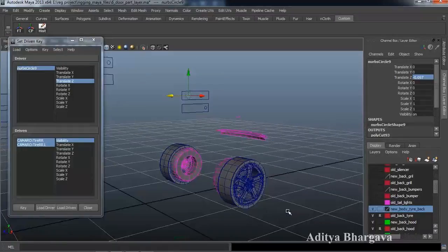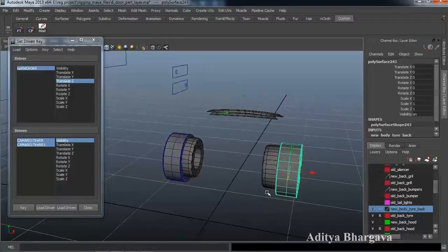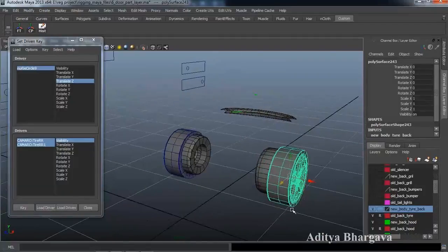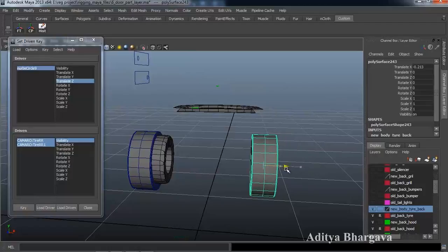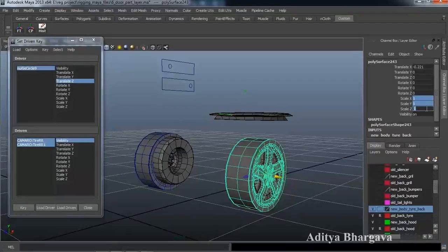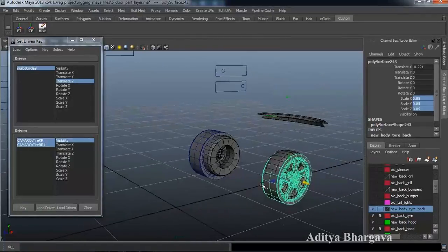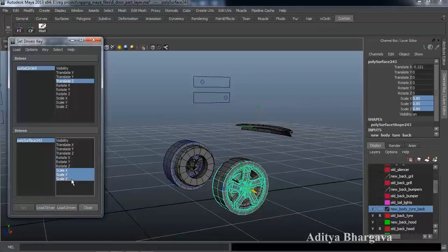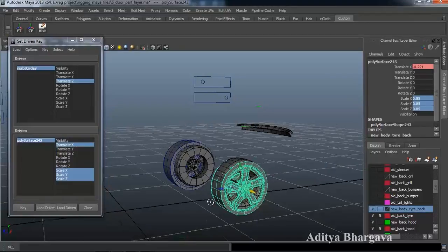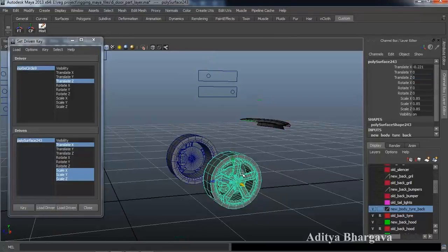And now what we have to do is we'll start the tires at this position in the first frame. So we'll move the tires inside like this much position, and their scaling value to be 0.85, and we'll make it the driven object. We'll select its scaling values and the translate X value, and we'll add a key. Control Z. We'll take the controller value to the final value of the old layer where the old tires go off the visibility, and we'll put a value of the new tire from there, and we'll add a key.